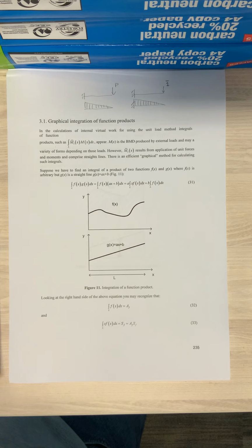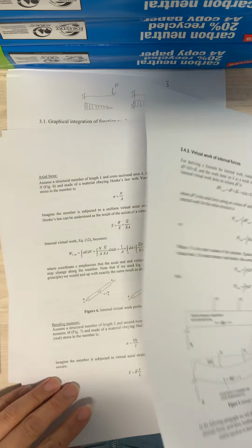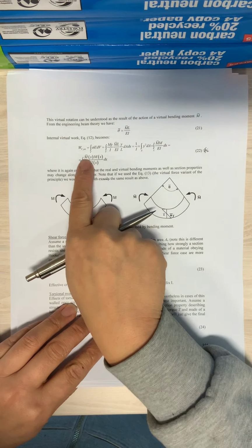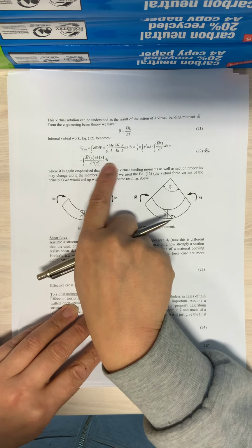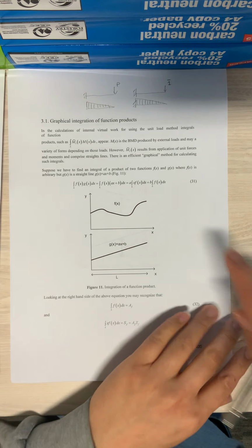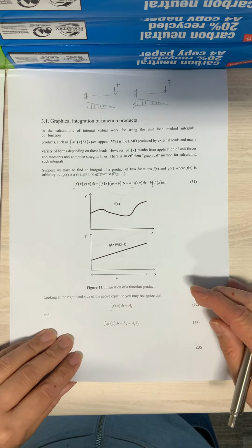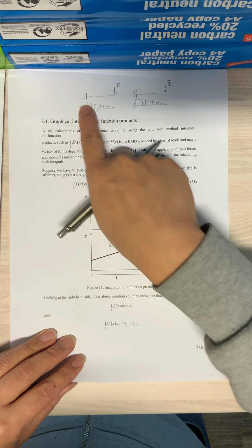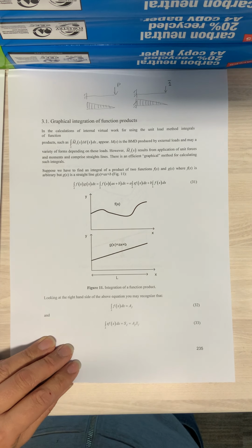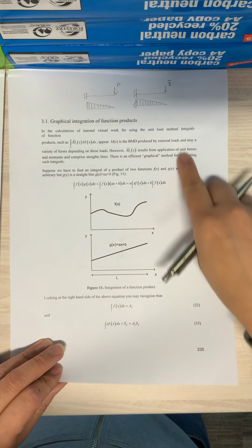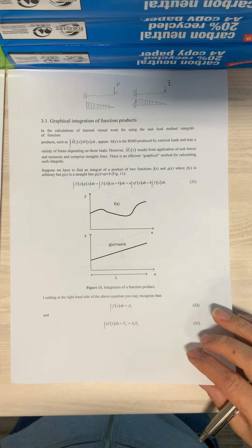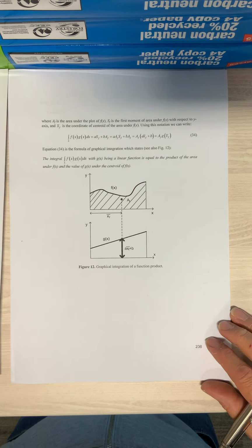So you may or may not have observed that when we flick through, and when we look at equation 22, you may or may not have noticed that that's an integral of two bending moment diagrams divided by EI. So there'll be fast ways to do the integration. You can do it manually, just work out some functions, multiply the two together, and then use that. Or there are some techniques which would speed up your ability to integrate functions.